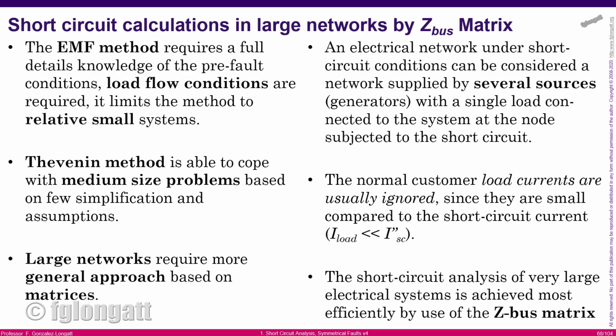Well, as we discussed before, the Thevenin method and the EMF method are used for short circuit analysis. The EMF method requires the full understanding and details of the pre-fault conditions, and that is coming from the load flow. And the Thevenin method by hand can be used for medium-sized problems. But if you need to calculate short circuit currents using a very big, large network, you need to use matrices. Okay.